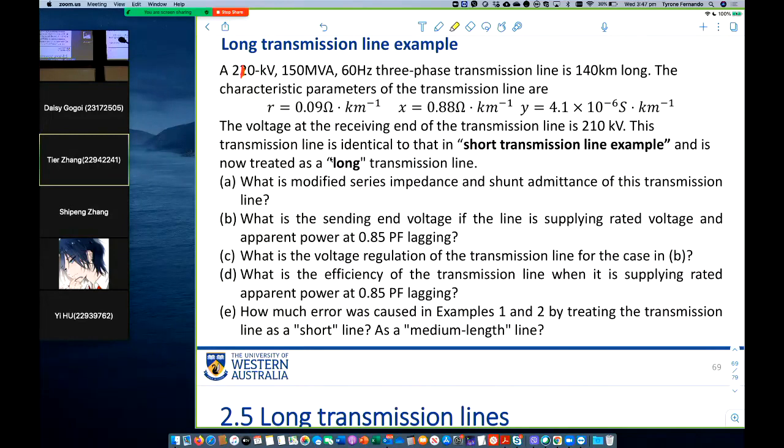Power factor is the angle between the voltage and current. Receiving end voltage is given, but the phase angle was not given, but we can choose the receiving end voltage phase angle as our reference, as angle 0. Because when we talk about the power factor, we are talking about the power factor at the receiving end and the load on the receiving end. Do you follow me?